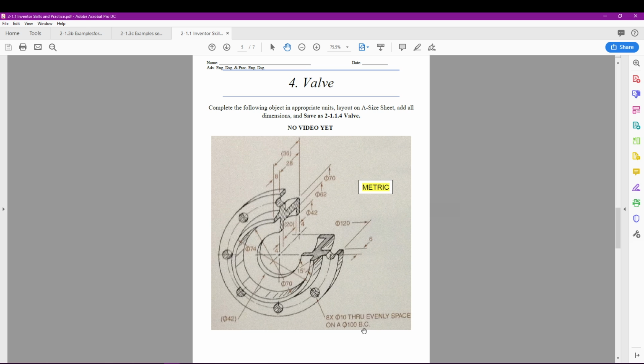Okay, so as we're looking at everything, we also notice that there is this big chunk of it taken out. This is called a half section, and what it's done is it's just removed a portion of this so that we can see what the inside looks like. This helps when we are laying it out so we can properly dimension everything. We see that we have one central axis line right here. This is our main center axis. This is our origin, and we're just going to be doing everything on this.